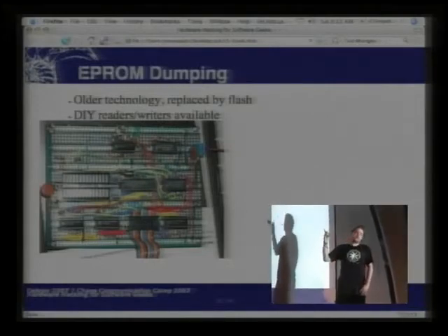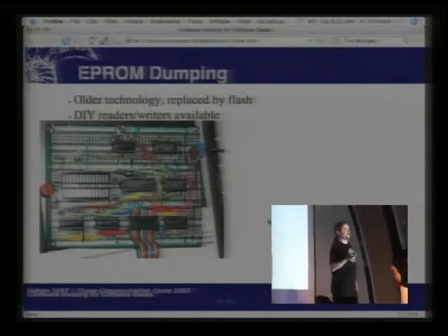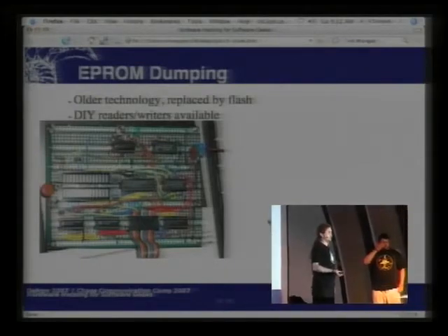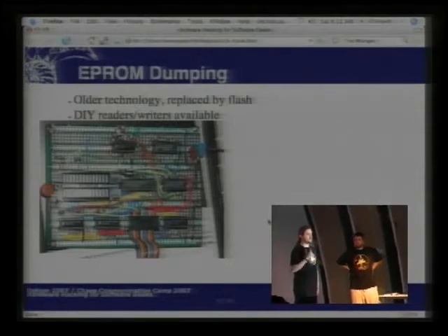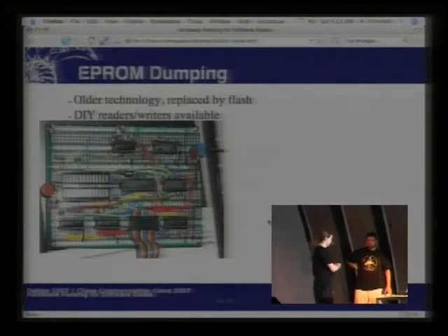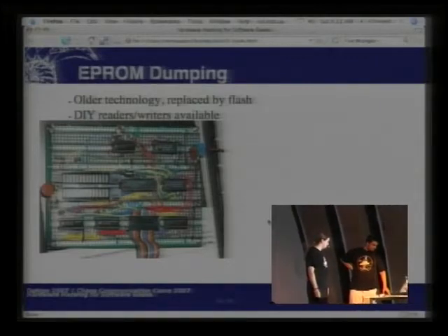The thing is, EPROMs are fast disappearing. They're an older technology, they're less easy to work with than Flash, and possibly less reliable. They also come in smaller sizes. Flash has kind of replaced them, and if you want to dump flash memory, you might do something like this.